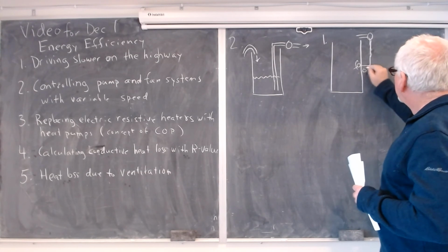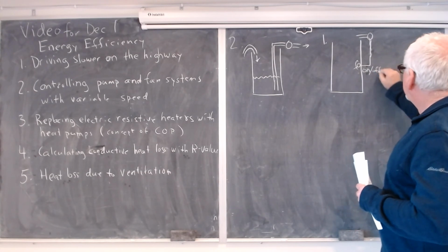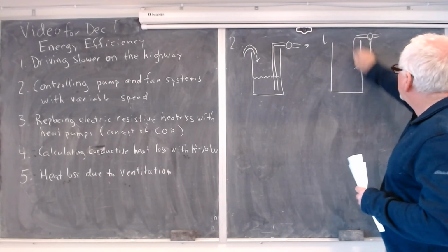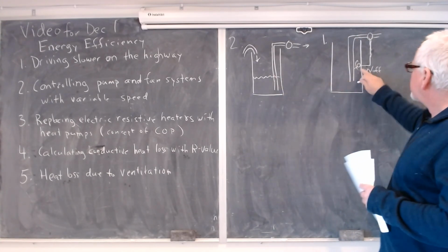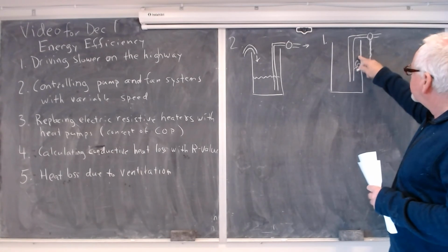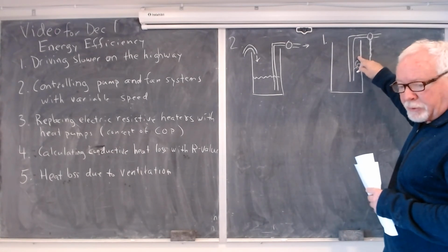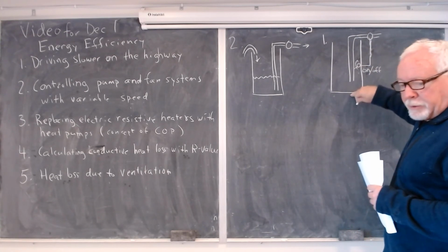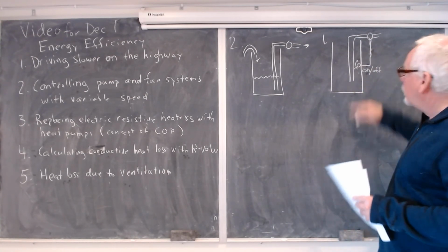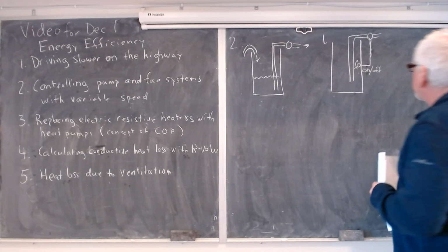So this is on, off. Basically, the idea is that when that water gets up to that float, it lifts it up and it switches the pump on, and the pump pumps the water off until it drops back down below the level where it switched the pump.